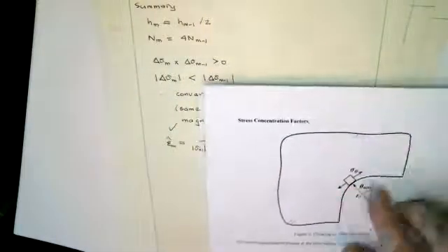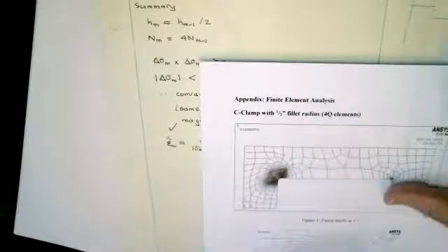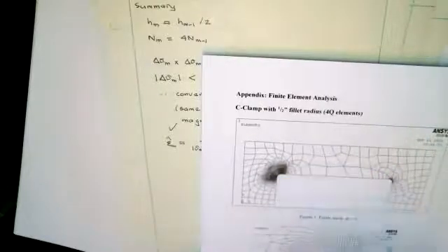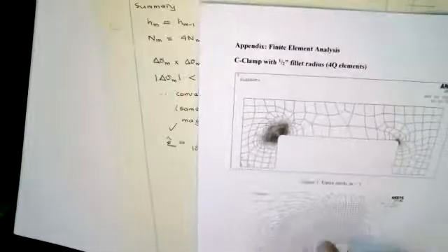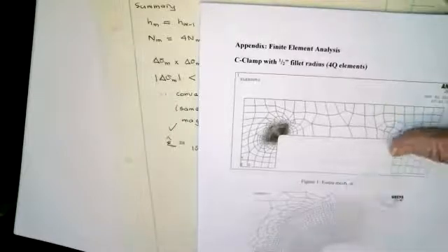This is this peak stress here. There's a sequence of meshes. Here's the original first mesh. It's refined near the area where the peak stress is. It's actually very structured here, so the elements here are being literally halved. But there are some transition meshes where they've been halved on average.